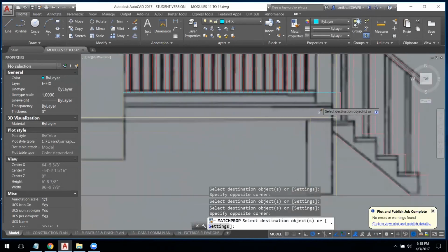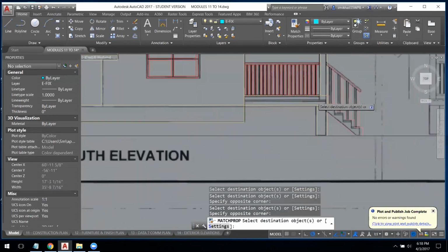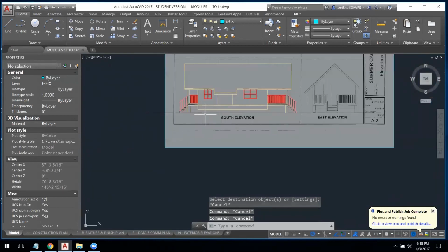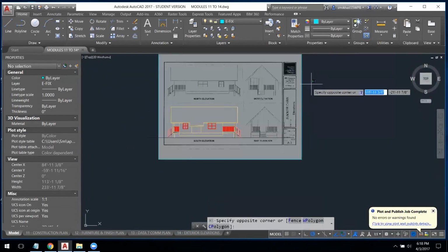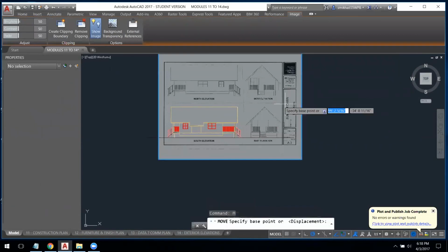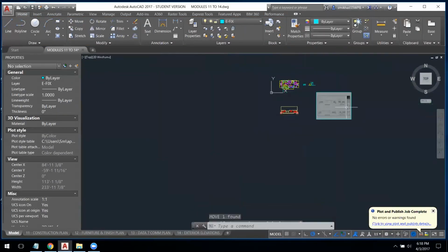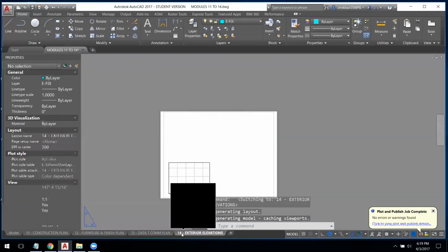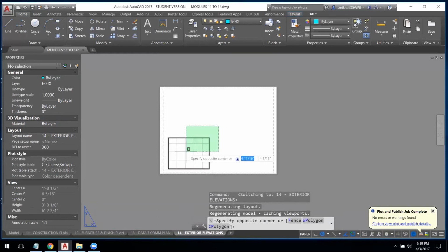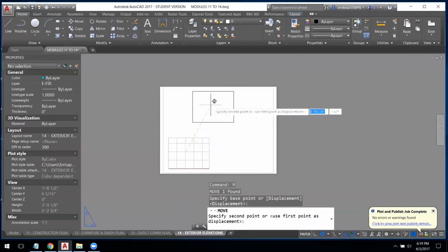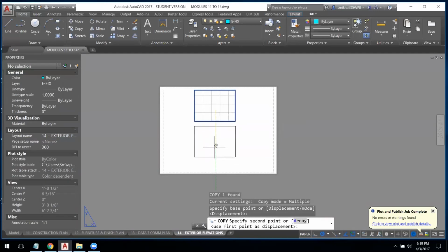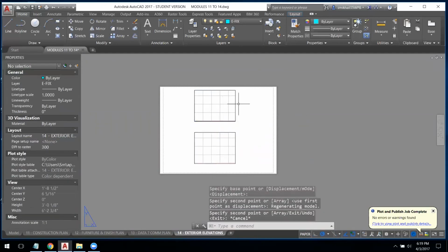Ground planes are usually dark, so we're going to make those dark. Okay, and let's take a look at it now. We can take this now and move it away since we don't need this as a reference here anymore. Here is our elevation. And if we go to the 14 exterior elevation, we can take this viewport and copy it. We need two of them, one for each elevation for our assignment.